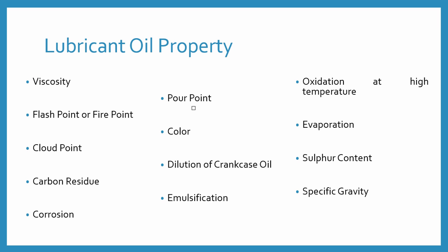Below this temperature, the oil becomes plastic, so it does not produce hydrodynamic lubrication, and therefore it cannot be used below this temperature.